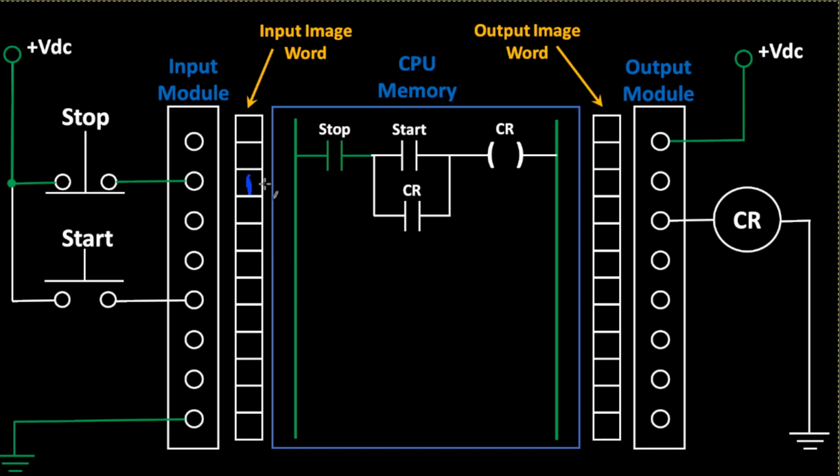Normally open contacts are closed. Normally closed contacts are open. Now that's not a relay coil, it's a bit in memory. But the bit is a 1 or on. And when the bit is a 1, any instruction that's programmed to it will be in the opposite state of the way it was programmed.